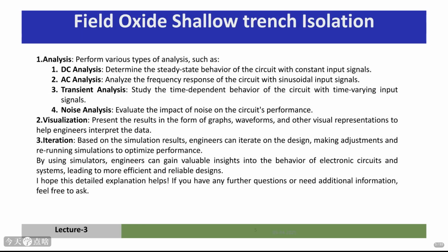Okay, so you've built your virtual model. Now what? You perform analysis. This is where the simulator gets to work. You can ask it, what happens when I apply a constant voltage? That's DC analysis. Or, what happens when I feed in a sine wave of different frequencies? That's AC analysis. Maybe you want to see how the circuit reacts over time, like when a signal turns on or off?